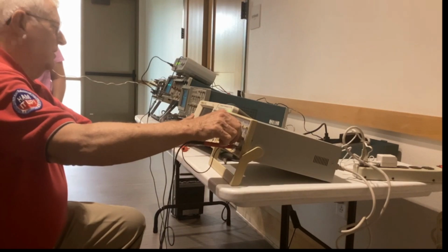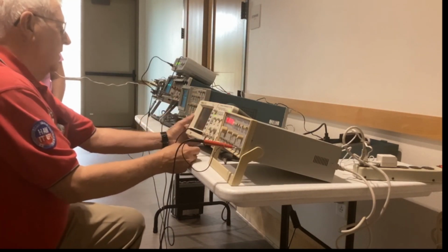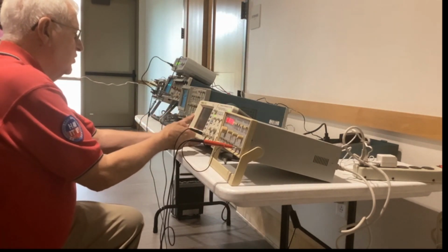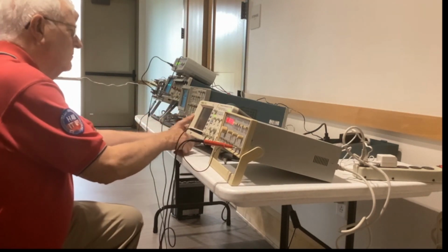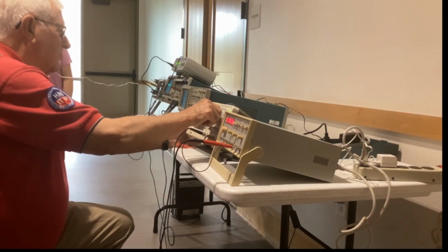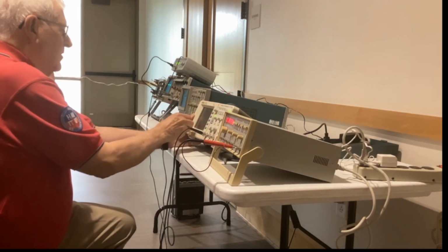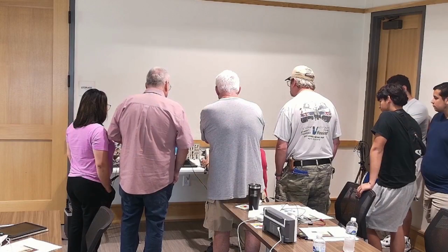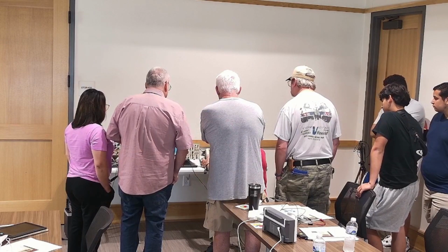Take it down to about 10 volts. And we're on 2 microseconds per division here. This is where I can move it back and forth. So if I go right about there, and I measure from here to there, so at 1, 2, 2.5 times 2 microseconds. 2.5 times 2 is 5, so 5 microseconds.